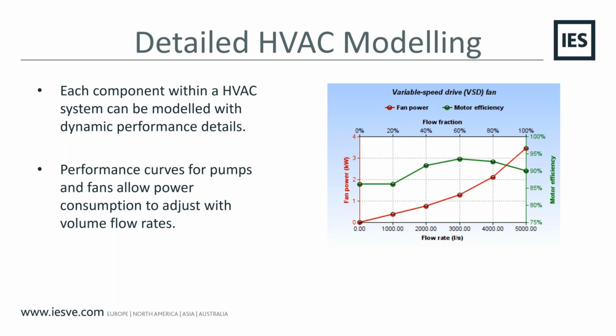Now, depending on what configuration is used, if the ventilation was going onto the back of the fan coil unit, then that fan coil unit is going to have to run throughout all the occupied hours to ensure that ventilation gets applied. This can have a significant impact on the resulting fan energy, and this type of analysis using a detailed HVAC model will provide the designer information on the implications of these design changes.